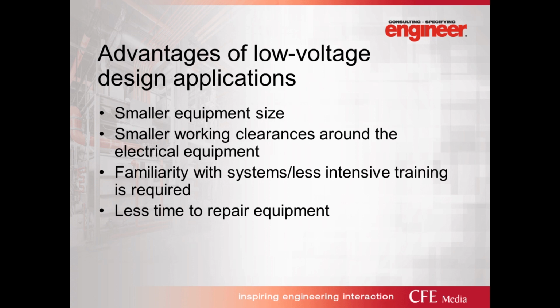With that, I'm going to turn it back to Jane to talk a little bit about the advantages of low voltage. Thanks, Ken. So just to clarify, we're comparing bringing a low voltage system into the building versus bringing a medium voltage system into the building and then stepping down to a low voltage system inside the building. The low voltage equipment has a smaller size than the medium voltage and requires smaller working clearances around the electrical equipment.